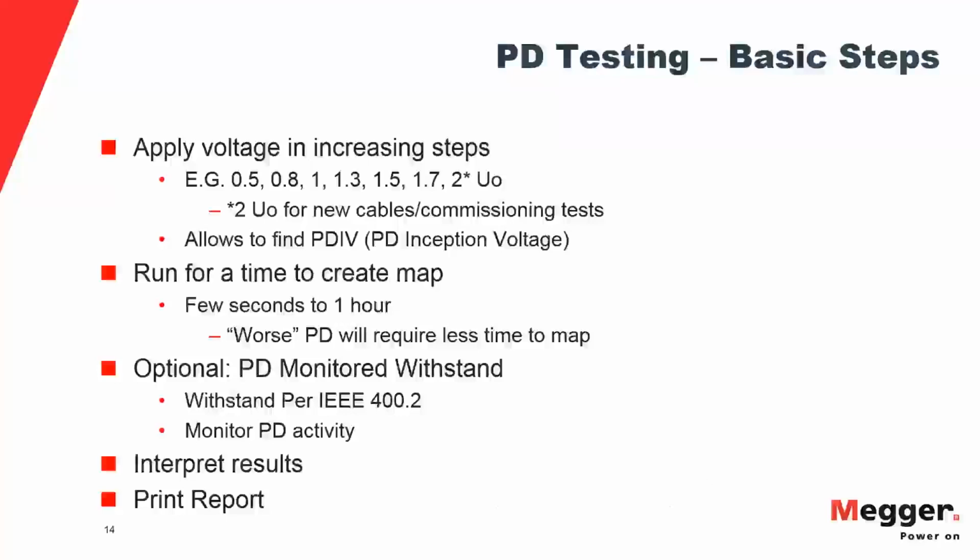We can look for workmanship issues in the splices and terminations, such as incomplete shrinking, misaligned accessories, things like that. There is some information given in IEEE 400.3, but there's no real standard available for partial discharge testing in the IEEE world. There's been a lot of work done in the IEC world. It's been well known for many years there, and they have a little bit more information in the IEC standards.